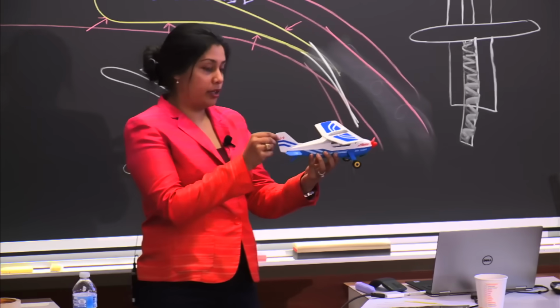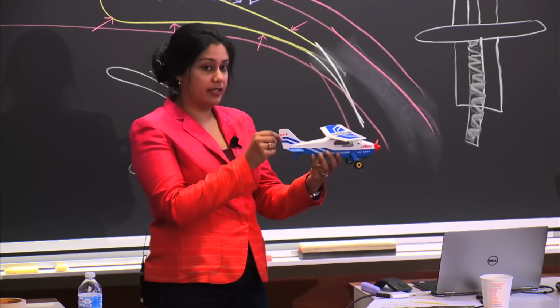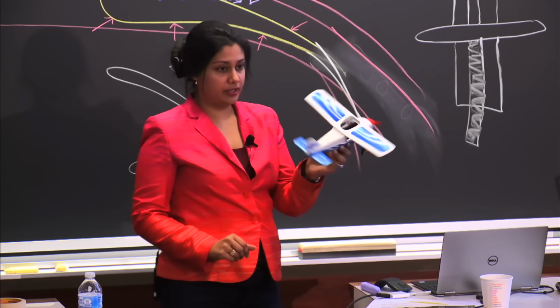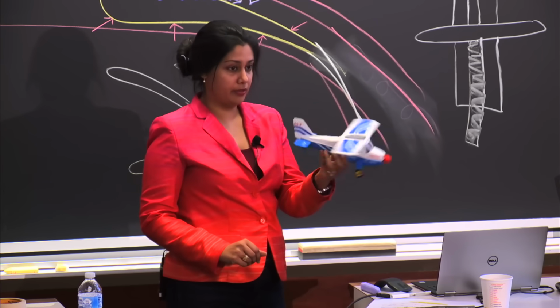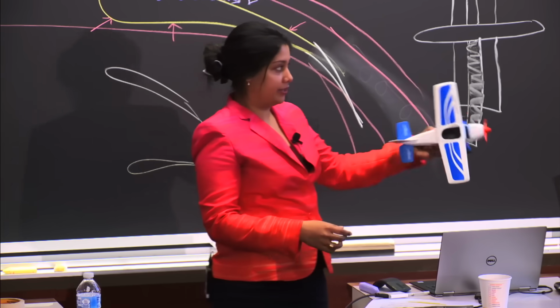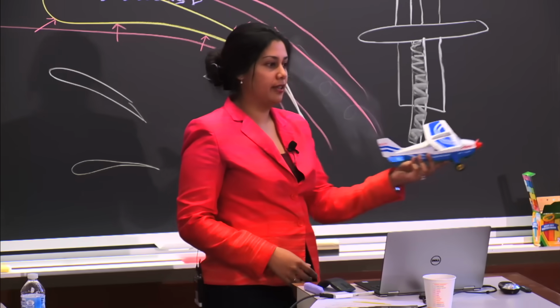And then your rudder, which is at the back of the tail, the vertical part of the tail, controls yaw. So this is called yaw, this type of motion. So when you're turning, you actually do a roll and yaw, usually, to enact a turn.